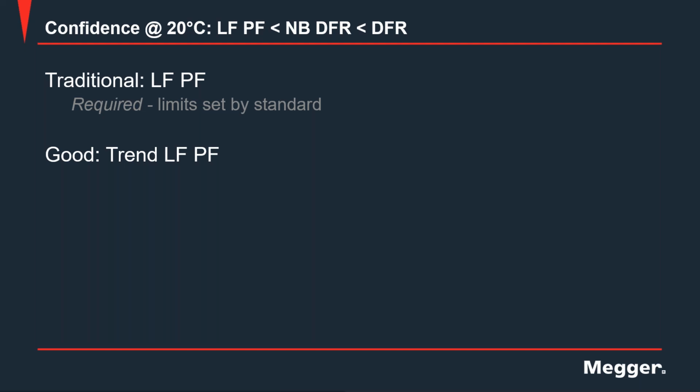But now you're looking into how this is changing. And if you are able to properly correct to 20 degrees C, then you're going to see very interesting things. The problem that we have seen is if the insulation is changing, of course, you may not see the influence of temperature if you do not correct that properly. And that's the reason for individual temperature correction.